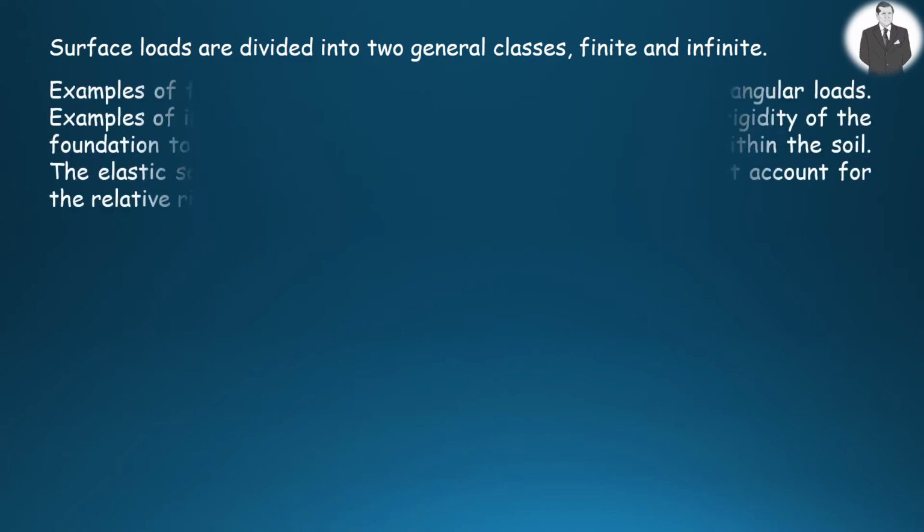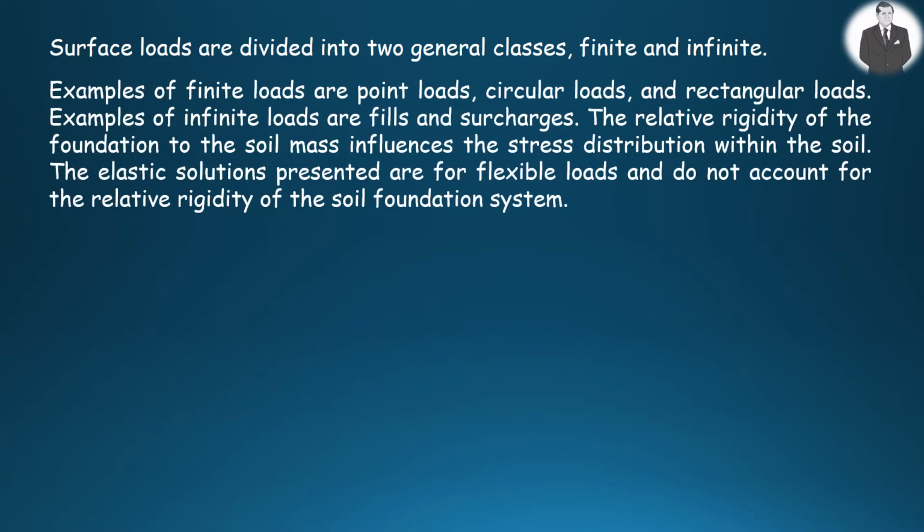Surface loads are categorized into finite and infinite. Examples of finite loads are point loads, circular loads, and rectangular loads. Fills and large surcharges are examples of infinite loads.